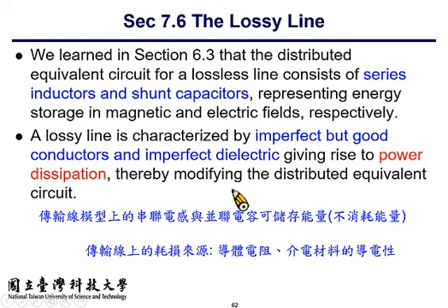And the imperfectness of the dielectric material, that is a very small conductivity within the dielectric, exhibits the so-called conductance in the dielectric. Because of this mechanism and the way it attenuates the signal, it is represented as a shunt resistor in the distributed circuit, or you can express it as a conductance in the circuit.